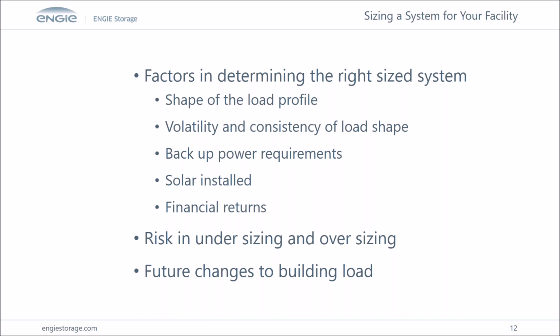Is solar installed? We typically see the battery ratio between solar and storage. If you have a megawatt of solar, you're typically looking at about a 500 kilowatt, 1 megawatt hour battery system to pair up to that. And then obviously financial returns, right? Because if you can use a smaller system at a comparable risk, you're going to get better savings on the financial side.